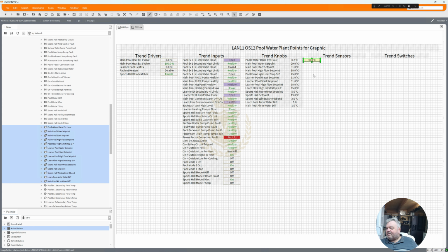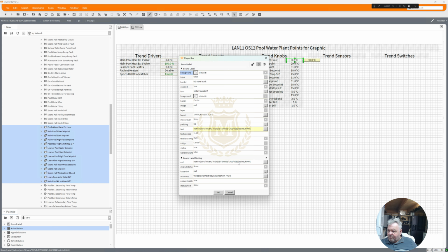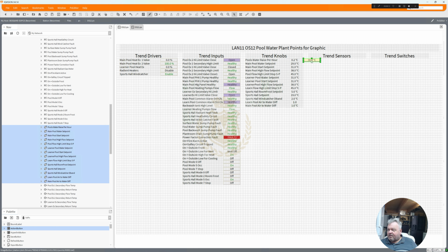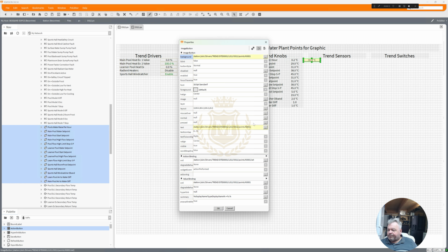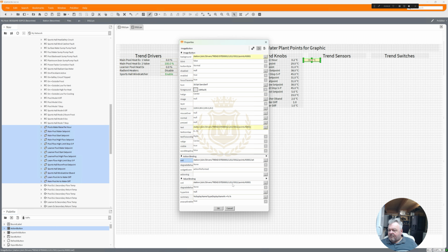The device limit is 0, so we're upgrading the license. So instead of just twiddling my thumbs and doing nothing, I thought I'd make the PX pages here on the station, and then once the license is done and we can go to the supervisor, I can copy these pages across and then do a global command to point them to the Niagara network, and I don't have to redo all these again.